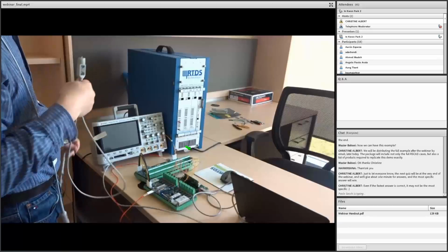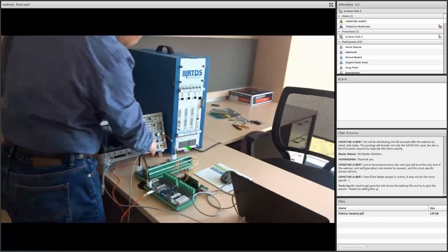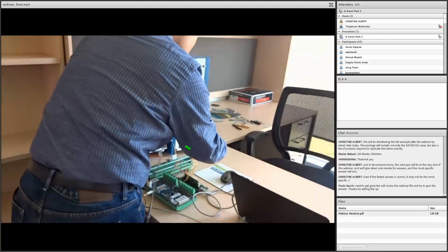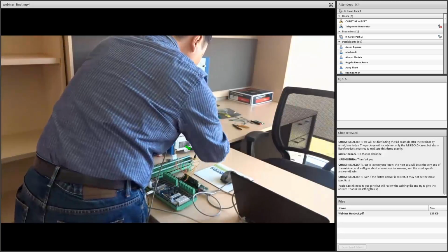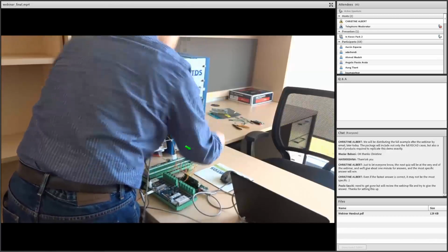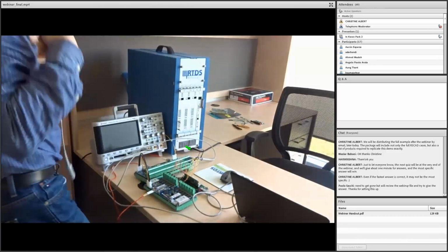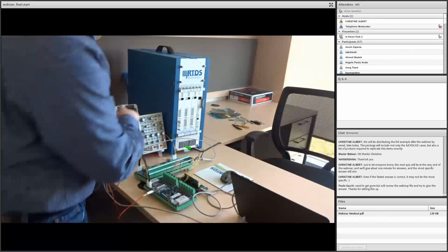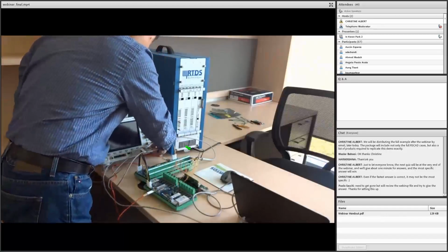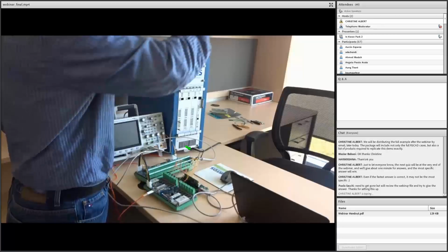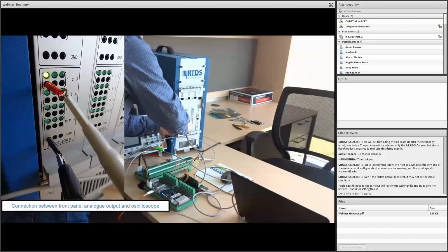And that channel is representing the gating signal coming into the number 1 valve of a 2-level bridge. That number 1 valve is the upper side valve of the A-phase arm in your STATCOM or 2-level bridge. So when that valve turns on, the node voltage in front of that A-phase arm becomes the plus DC rail voltage. Or the other way around, when the switch goes off, then the bottom valve will turn on, and that valve will connect the minus DC rail voltage to the node voltage. So this is how it looks at the RTDS side.